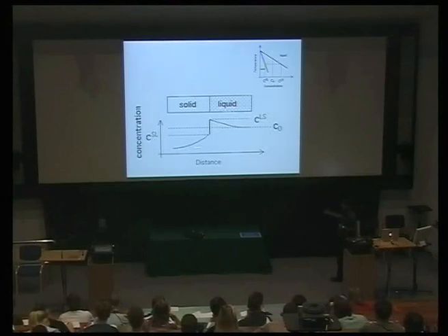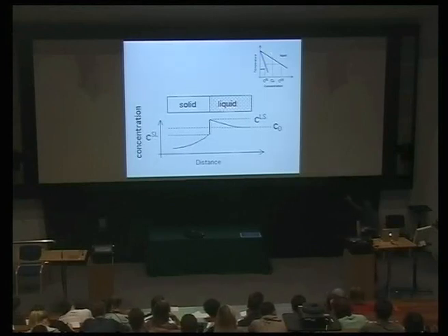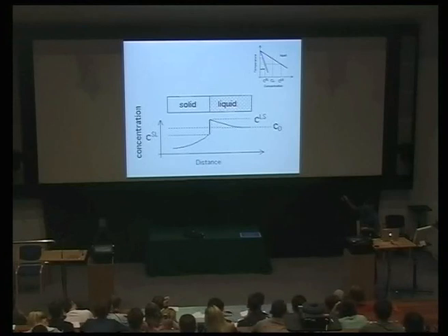Okay? Now, this is increasing in the solid. The solid is not homogeneous because we started solidification at this temperature. And at that temperature, the equilibrium composition of the solid was small, and it increases as solidification proceeds. Yeah? Is everybody happy with the fact that this should rise as I go down in temperature? Yeah?